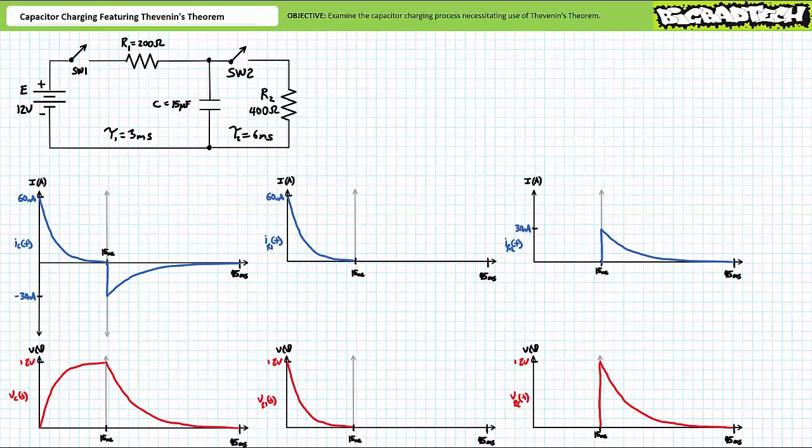We've discussed all sorts of capacitor scenarios, and the process by now should feel pretty formulaic. If it doesn't feel formulaic, you're doing it wrong, and you need to revisit and review the aforementioned lectures until it does. If you haven't figured out the formula just yet, here it is. Determine the start point, determine the end point, determine the time constant. Pull the pin and throw it.